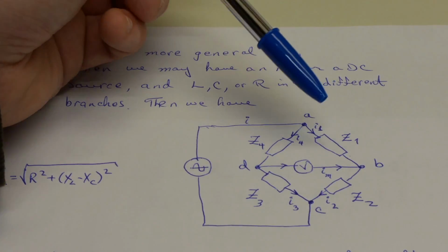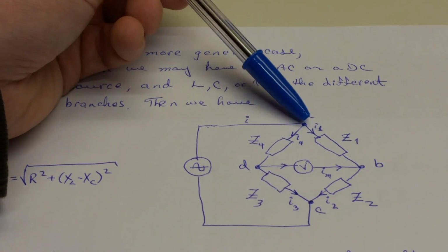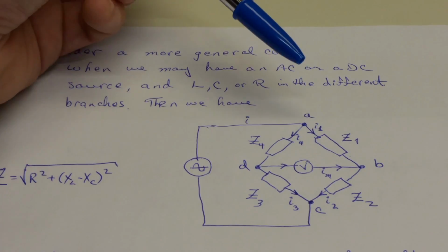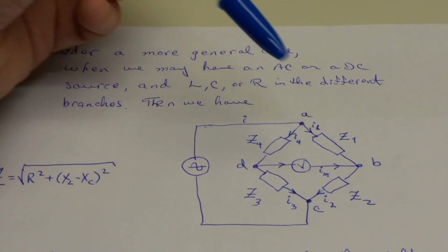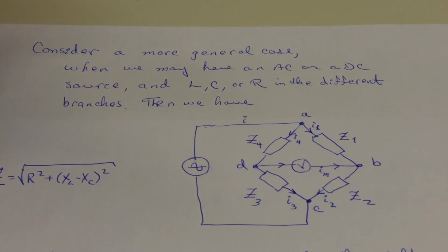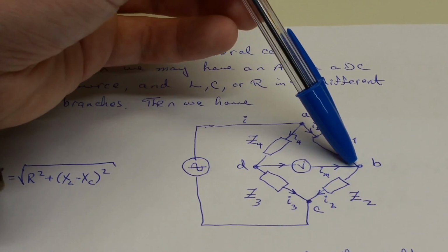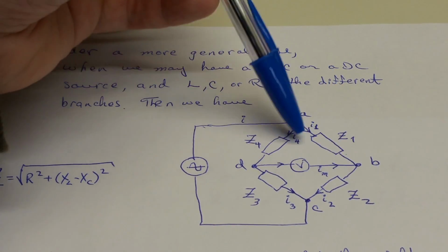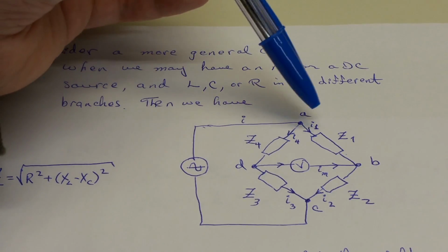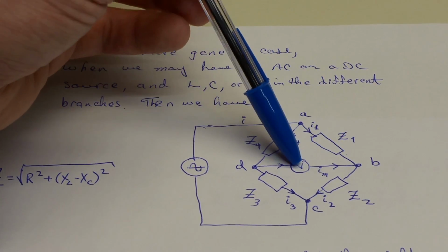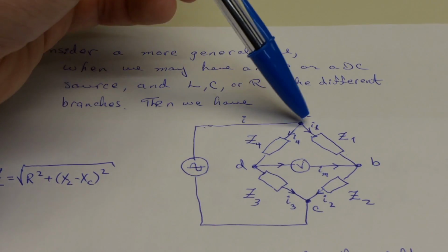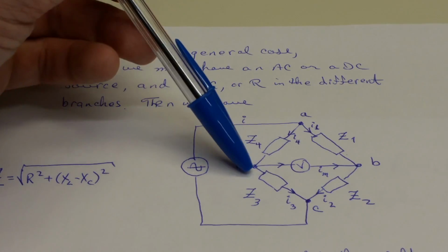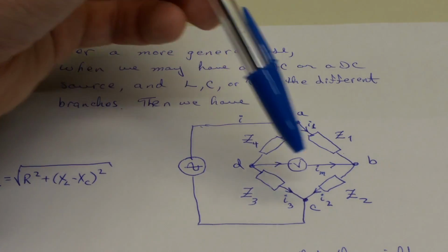So the first equation is going to be the potential difference across this resistive element, this complex element, the Z1, is going to be I1 Z1, just applying Ohm's law to that. And then there's going to be minus IM, because the sense of the loop is opposite to the current flow in this direction. So we have I1 Z1 minus IM RM, Ohm's law applied to the voltmeter. And then we're still going counter to the flow of current, so this is going to be minus I4 Z4. And all of those things have to add up to be 0. So that's our first